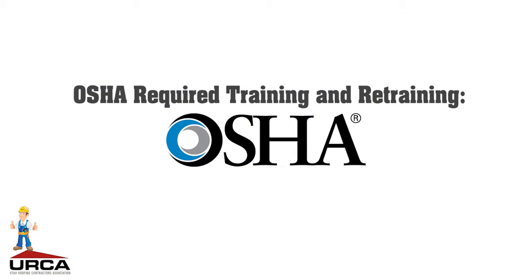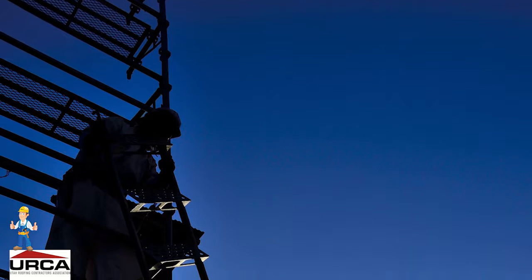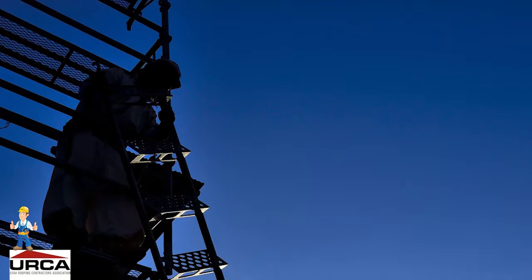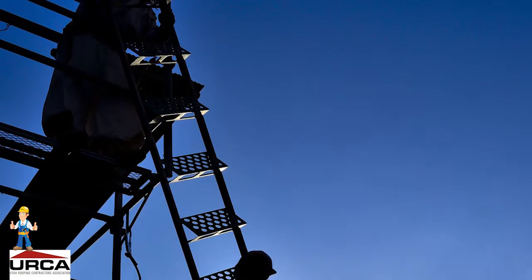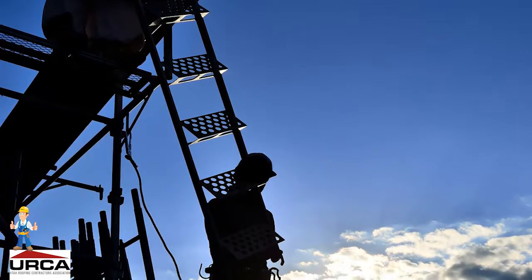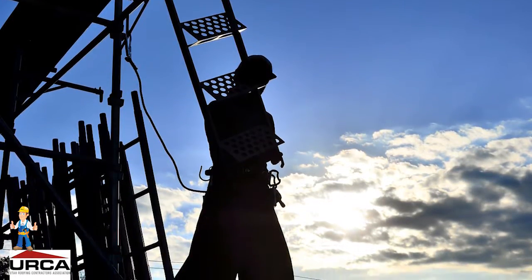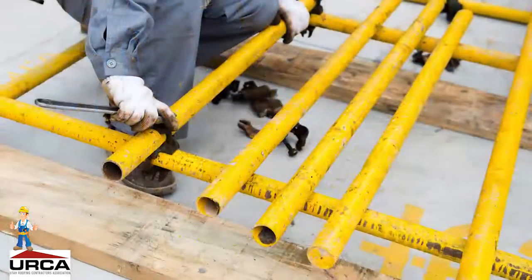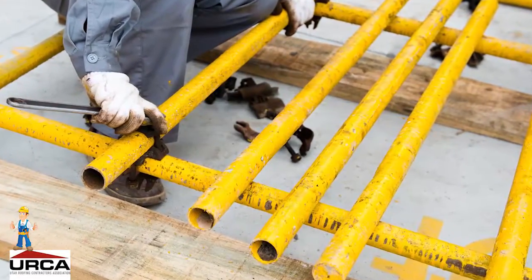OSHA required training and retraining. OSHA requires training and retraining under the following conditions: change at work site that presents a hazard for which the employee has not been trained, change in scaffold type, fall protection system, or falling object equipment that present a hazard to that employee who had not been previously trained. Inadequacies in employee work indicating they have not retained the initial training.